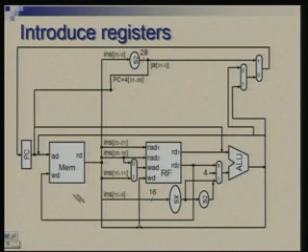We are reading two things, the instruction, and we are also reading the data which needs to go to the register file eventually. So, two registers will be required here, one will store the instruction, one will store the data. Then you are reading operands from the register file, they will be kept in small individual registers here. The output of ALU will be kept in another register here. So, these are the places where we need to put registers.